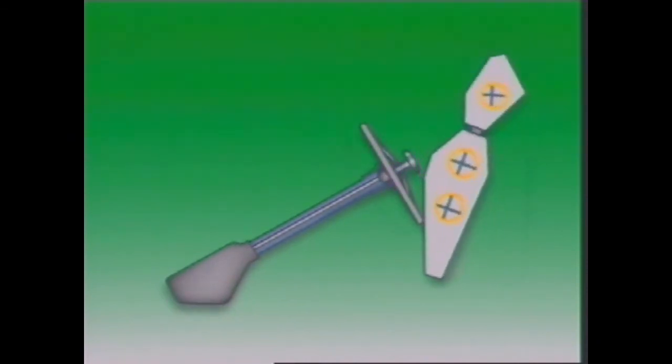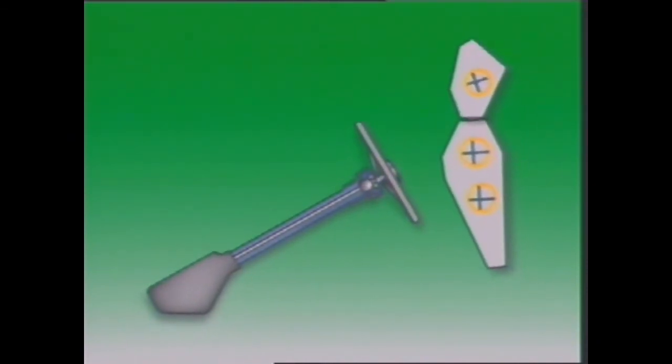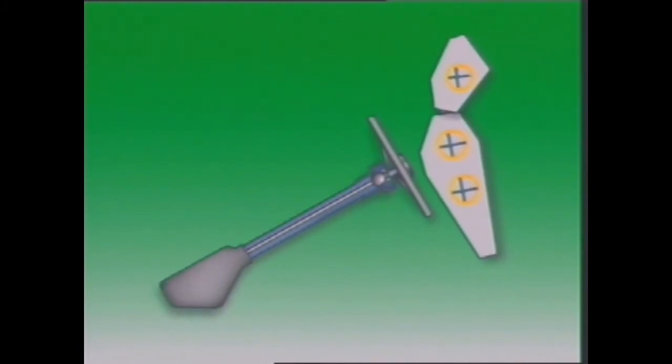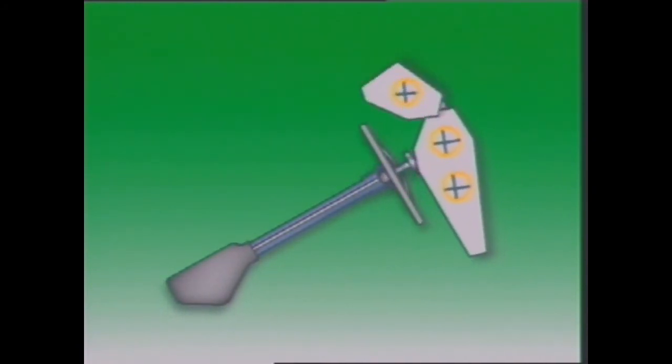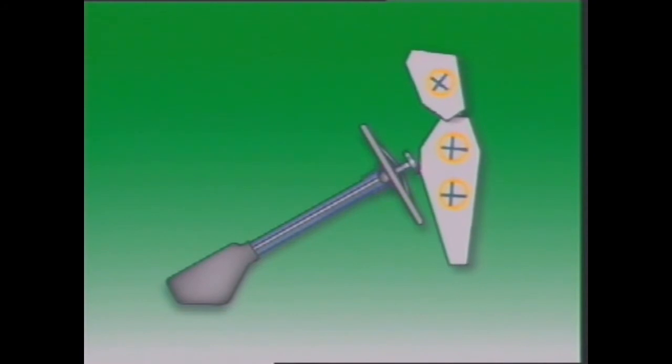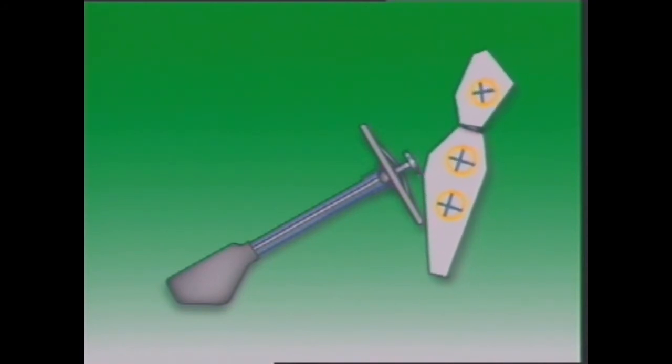In many frontal collisions, however, this caused serious injury to the driver, partly because it was forced back towards the driver's head, and partly because the sudden stop forced the driver onto the wheel. To reduce this hazard, some steering columns are fitted with collapsible sections that protect the driver. During a collision, two forces are applied to the steering column. The first is the force of the steering box being forced back towards the steering column and towards the driver.